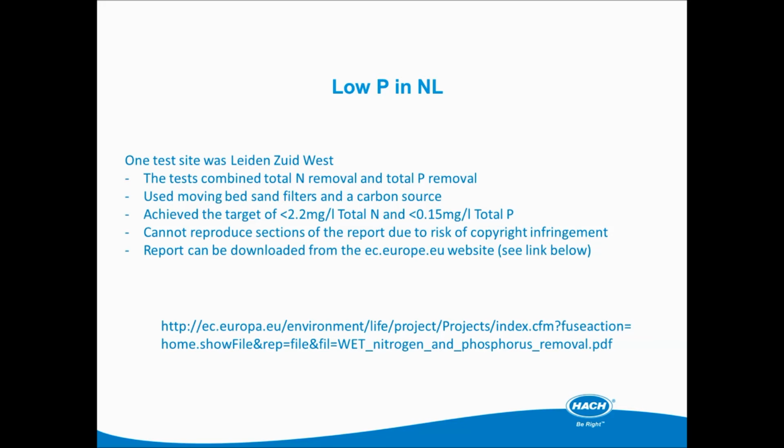The second stream had final effluent and carbon source dosed to the moving bed sand filter. Coagulant was added to the filtered water leaving the moving bed filter prior to it entering contact tanks. The clarified water exiting the contact tanks was then passed through a mixed media static sand filter, the same four parameters being monitored at the outlet of the filter as on stream A. Both moving bed sand filters were designed to operate as denitrifying filters, and the dual media filter in stream B contained a top layer of anthracite and a bottom layer being quartz sand. This was backwashed when required.